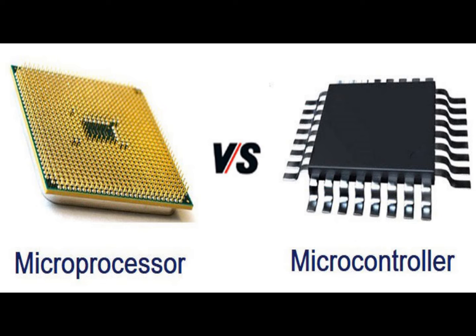A microprocessor is a single integrated chip that contains a device's CPU. However, it does not include any RAM or ROM memory or other peripherals that a device may have. Instead, the chip relies on input or output to connect to memory and peripherals. On the other hand, a microcontroller has the CPU, RAM, ROM, and peripherals embedded onto a single chip, which effectively makes it a computer on only one chip.